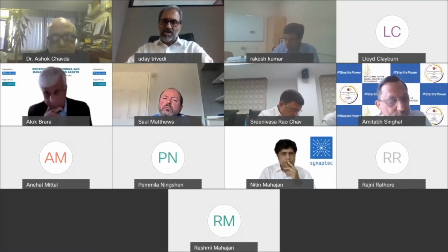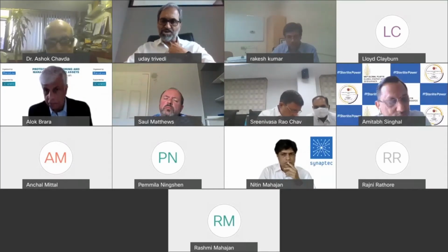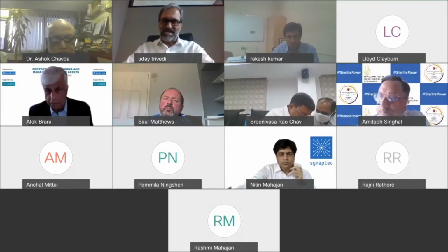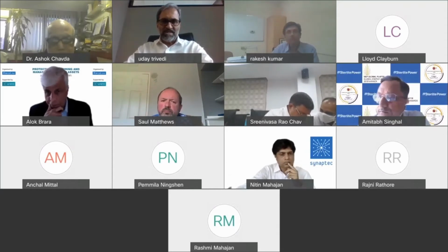Here I would like to mention what Mr. Matthews suggested, the technology being offered by him, because subharmonics is a major concern right now, and it can confuse the protections as well. Protections are designed to detect and filter some of the harmonics, but they are not immune to subharmonics. They are sometimes blind to subharmonics, and then there is a possibility of maloperation also.